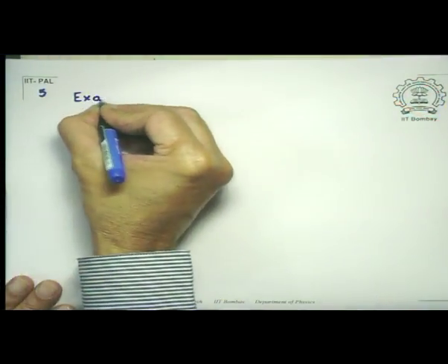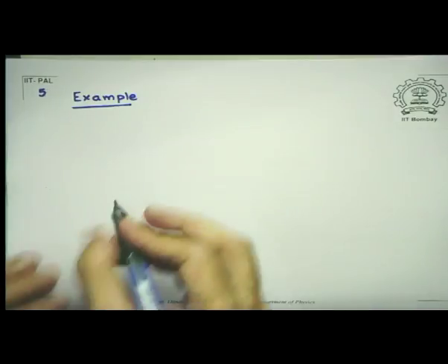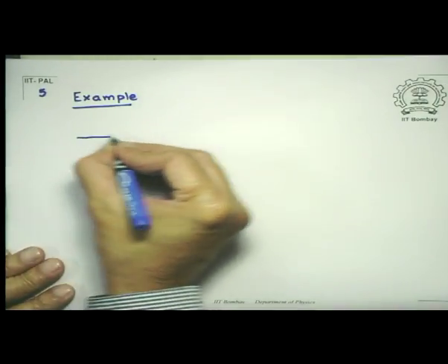So what we get as a result is 1000 plus 1000, I get 2000 milliamp hours for the same voltage, and as a result, of course, you can calculate how much is the power difference. So let me now use these to work out a few example problems which will sort of tell you in what situation you can use this combination to your advantage. So let me start with this.